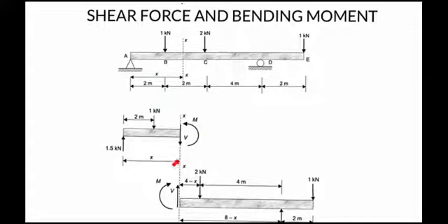The force V is the resultant of the transverse forces that are distributed over the cross-section at the section. This force V is called the shear force acting on the beam at the section X. It is an internal shear. The couple with moment M is the resultant of the distributed axial force that acts on the section X. It is called the bending moment acting on the beam at section X. Similar to V, it is an internal moment.